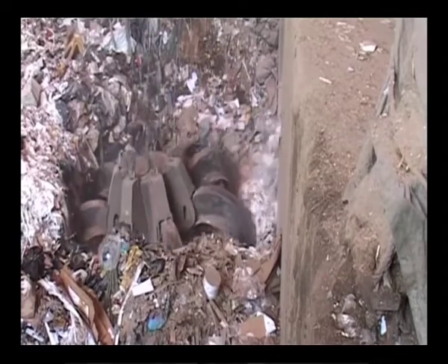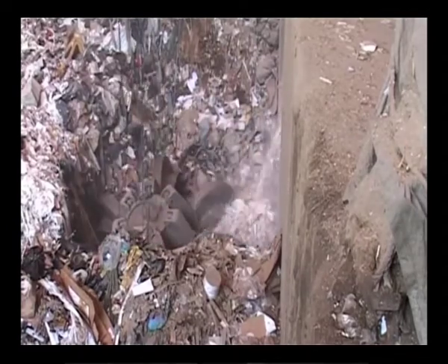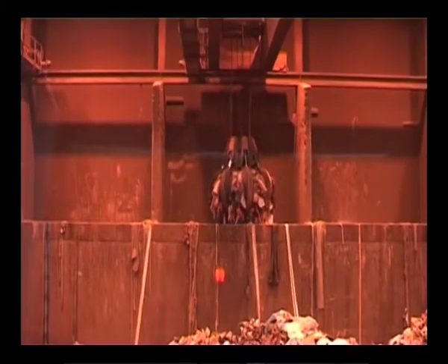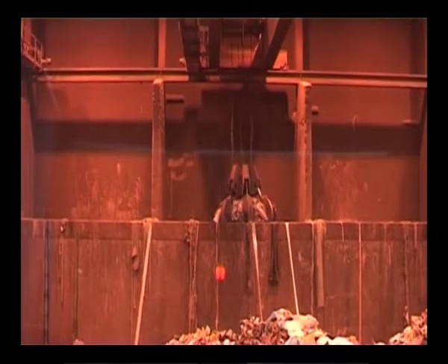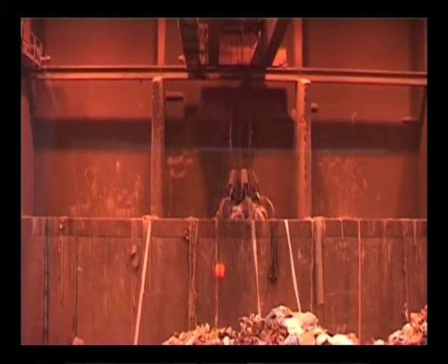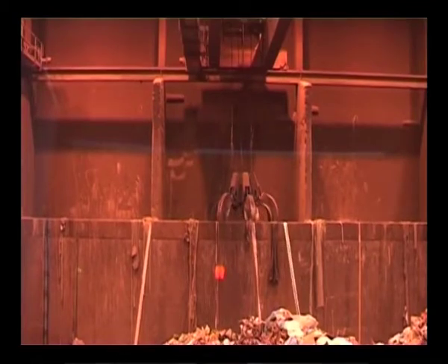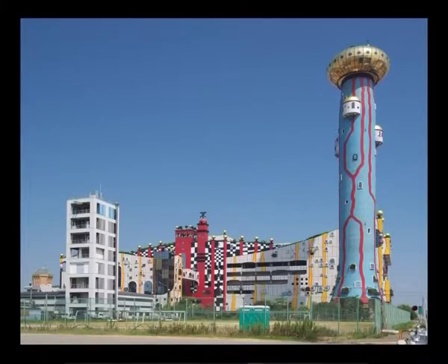Air is blown through the boiler another time, but this time comparatively faster than before. This air helps in complete burning of the flue gases with the introduction of turbulence leading to better mixing and excess of oxygen. In some grates, the combustion air at fast speed is blown in a separate chamber.